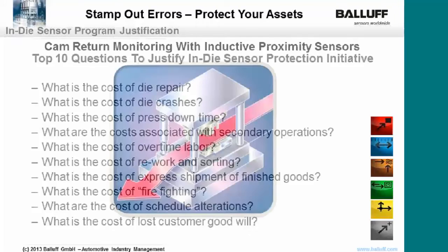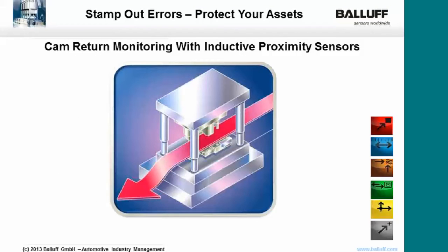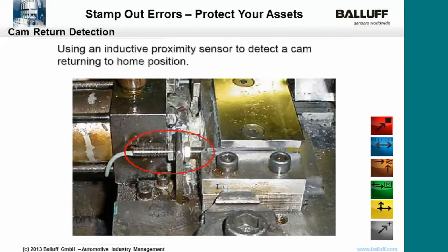It'll help you. First thing we're going to look at is cam return monitoring using inductive proximity switches. You can see the inductive prox switch at the bottom left-hand corner of your screen. Here we're using it to detect a cam returning to the home position.